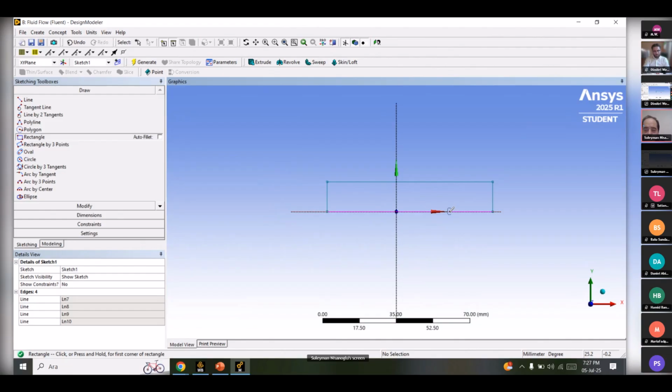You might recall from the analysis class in university that integrating an area in the radial direction gives us the volume. The ANSYS Fluent program handles this for us. We will select the axial symmetry option within the program after the meshing stage. Okay, we can draw this geometry. This part is half of the pipe.